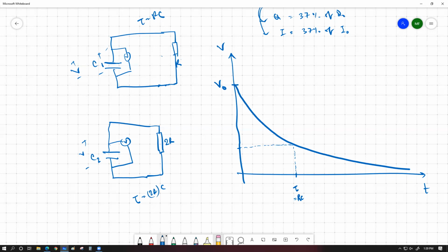It's going to drain slowly because there is a bigger resistance. It's going to allow the charge to flow out slowly. So it's going to take a longer time. In other terms, you can say that it's going to hold on to its voltage for double the amount of time. So simply, for the sake of drawing this second graph, I can simply double this time constant over here, let's say approximately over here, and take out this extension right over here. I get about this point.